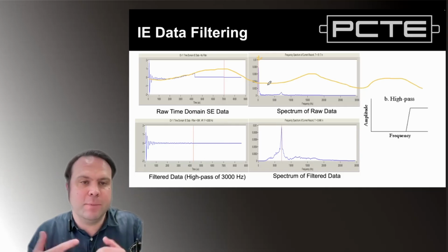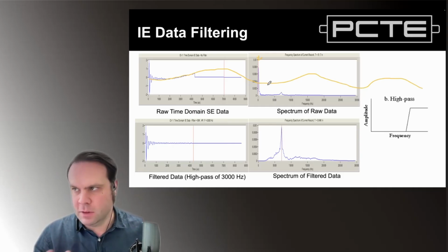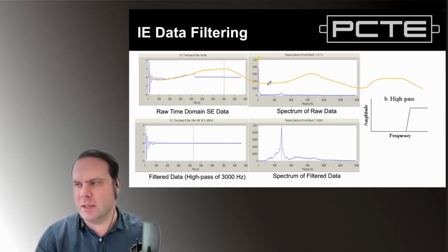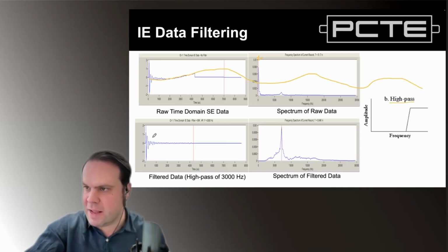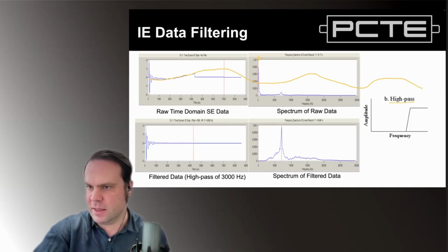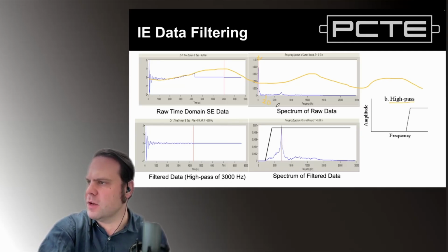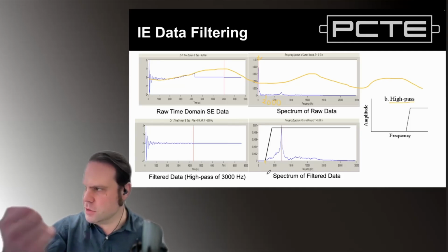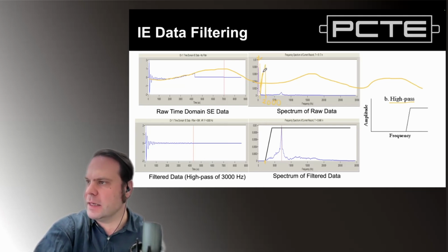Now, we could try and perfectly control the physical environment so there was no low frequency vibration at all on our sensor. That would be one way to eliminate this problem, but it's not practical. So instead, we'll use the digital high pass filter to convert our results, which on the sound domain chart look almost identical, if you see here. But what we've done is we've applied that filter, in this case about a 2,000, 2,500 hertz filter here. So we can see right at the point of that filter, there is no remaining response. And then, all of this information here has been removed.